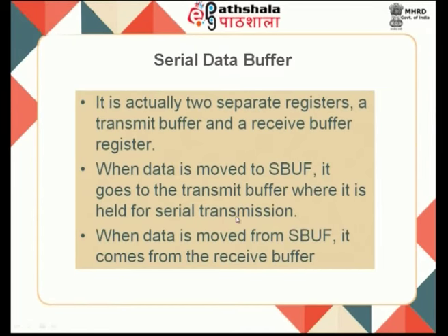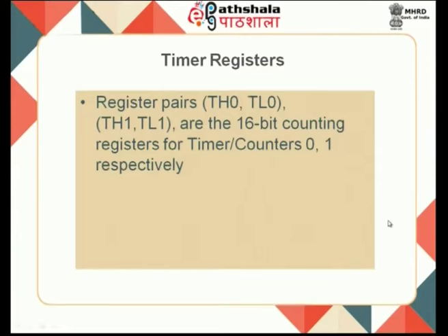Okay. So, the SBUF acts as the transmit buffer, where it holds the serial transmission. When data is moved from SBUF, it comes from the receive buffer. So, the SBUF is the interface between either the transmitter or receiver of a serial communication and the processor. Now, when you are looking at your timer registers, we have